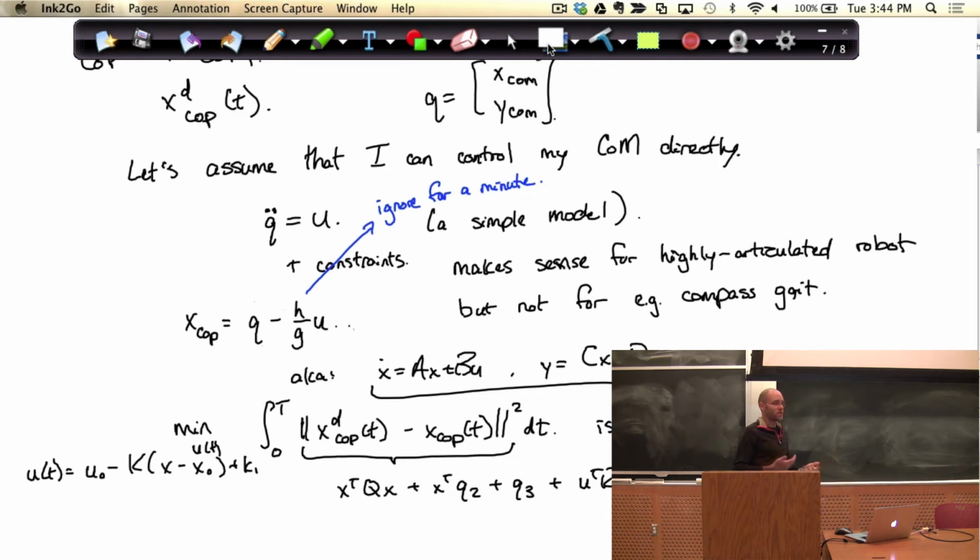There's people that, for instance, will try to make the center of mass look like a SLIP trajectory, and then use some of the dynamics we have for SLIP to try to solve for the long-term dynamics. If you wanted to make your robot run, that might be an idea. It's not my favorite idea, because I don't think that the humanoid should necessarily look like SLIP, where I feel like this is really the dynamics of the humanoid. And then my only assumption is that I can accelerate this directly. My objective might be wrong, but the dynamics are sort of real. With SLIP, I worry that you're imposing pogo stick dynamics when the robot might not be very good at that. But you could take that and impose that instead. Right? So that's the way to relate those ideas.